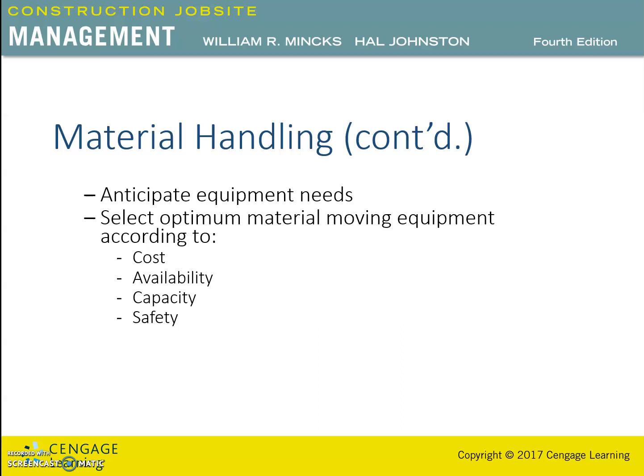Okay. The relative quantity of the material to be moved also is a factor when deciding what equipment to use. High mobilization cost can be absorbed if a large amount of material is to be moved. For small quantities, the contractor will probably use a labor-intensive method rather than pay travel or setup fees for lifting and moving equipment.